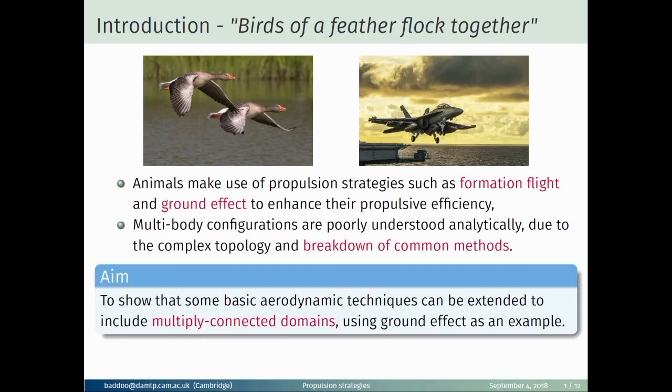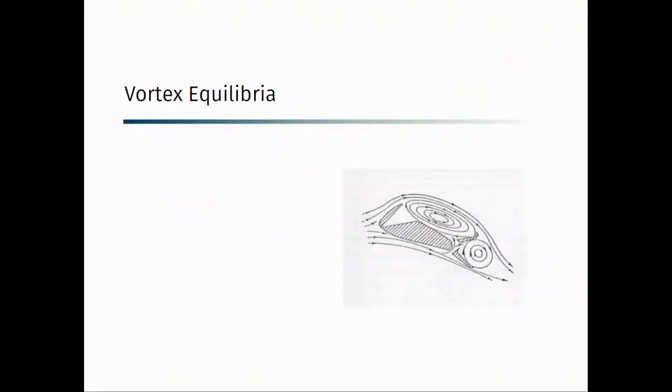show that simply connected, that is single-body, techniques can be extended to multiply connected, that is multiple-body problems. And we're going to be focused on ground effect for an example, basically because it's the simplest non-simply connected domain. And the two phenomena we're going to study are vortex equilibria and small unsteady motions. So firstly, the vortex equilibria.